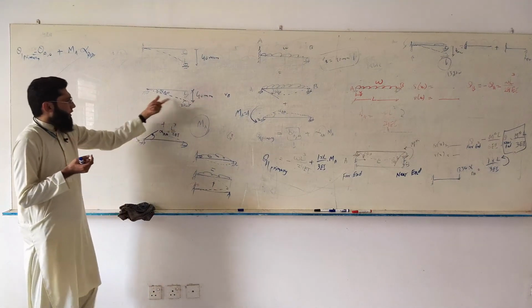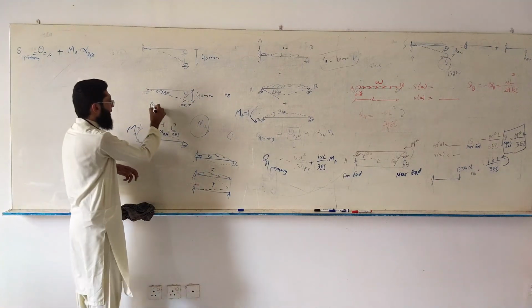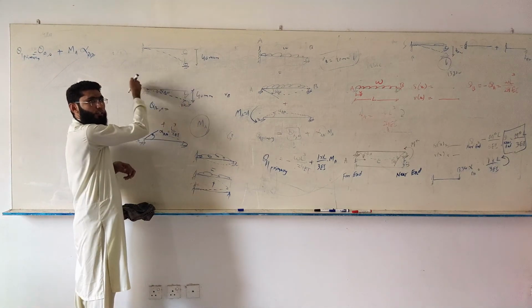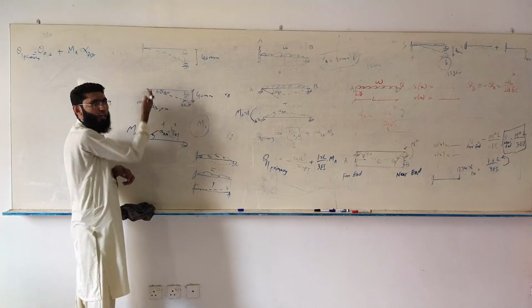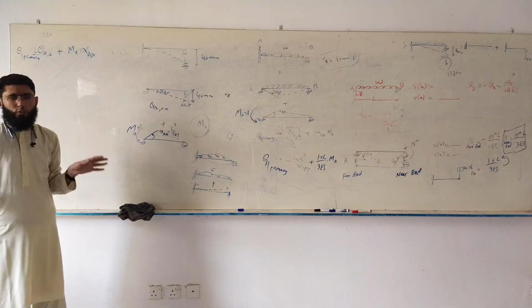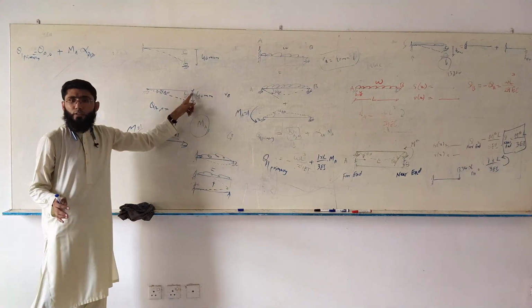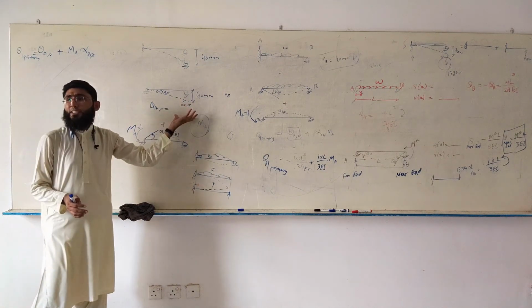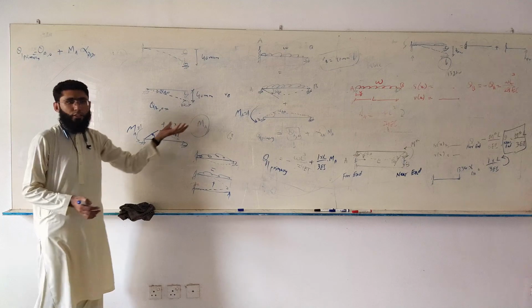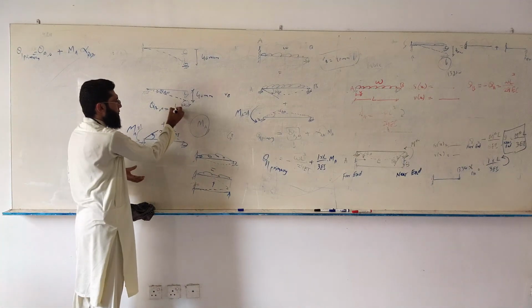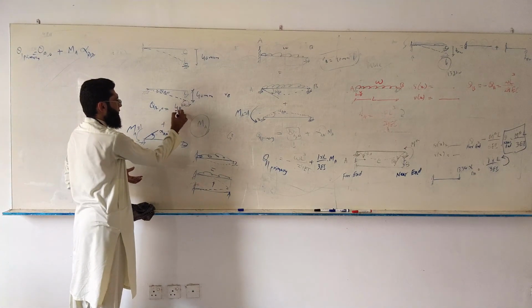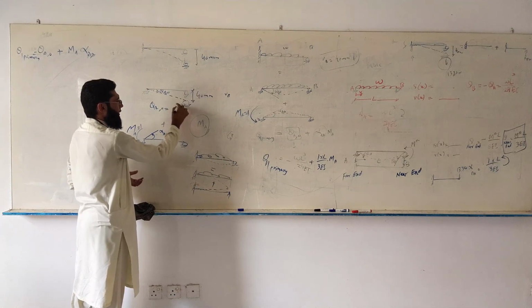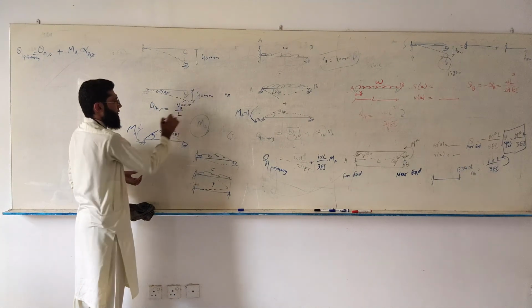So this is what theta A naught is. What is theta A naught? This divided by this. As long as it's a small value, it should be a small value. This is 6 meters, and this is just 40 millimeters, so it's going to be a small value. I'm showing it in an exaggerated way to make it easy to understand. So it is equal to VB over L.